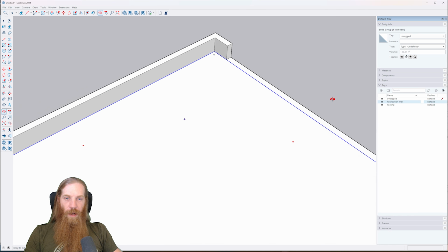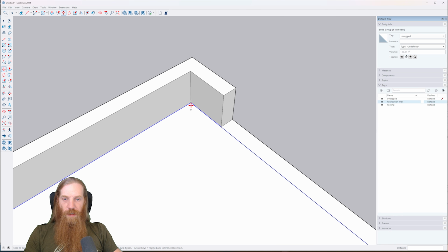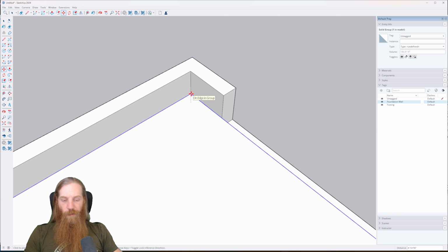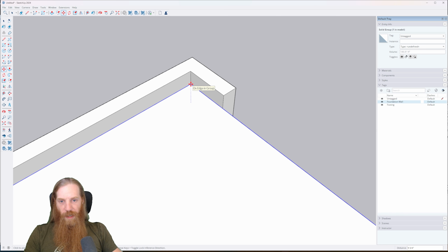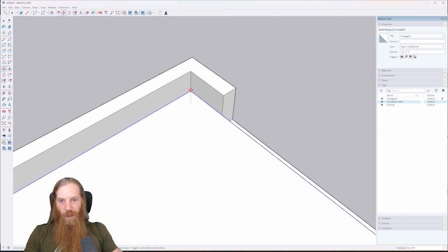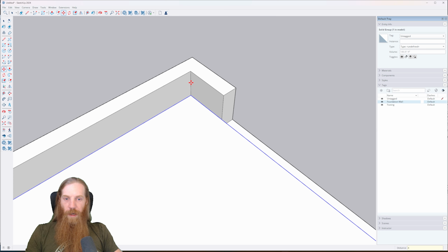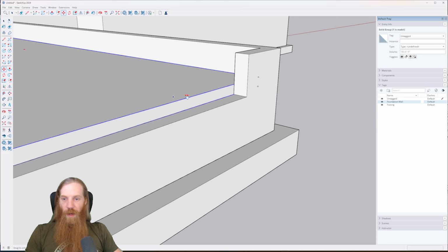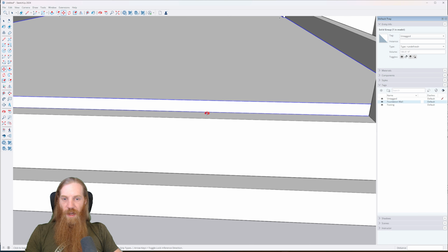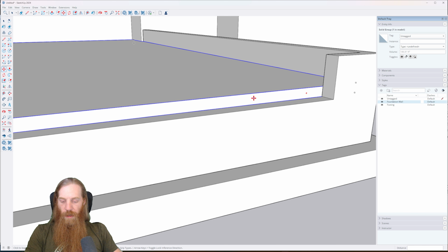It just had moved. Now what I'm going to do to move it up 4 inches, I'm just going to grab that corner up 4. So I start moving it up. I can see it's on the blue axis because I'm following the edge of that corner. So it's very easy for it to snap to that. And then I just type in 4, hit enter. It's now 4 inches above. So the bottom of the slab is hitting the top of that little cutout we made in this stem wall.